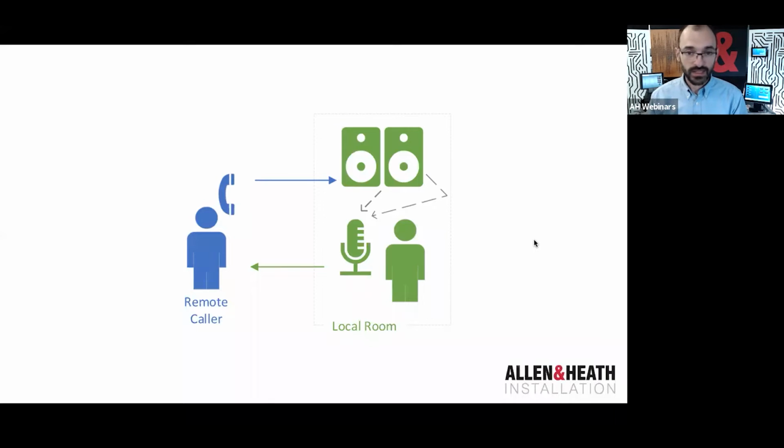And despite the advances in cloud processing technology with Teams and Zoom and so on, you've probably heard that echo at some point this year in your video calls, and it's a very common problem. So acoustic echo cancellers essentially try to avoid this problem by subtracting a simulated echo from the local microphone signal, or microphones, plural, if you have multiple microphones. So the signal from the local microphone is what we call the near end, as opposed to the far end, which is our remote caller.